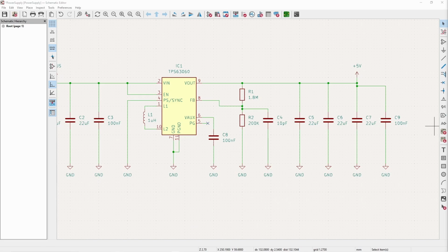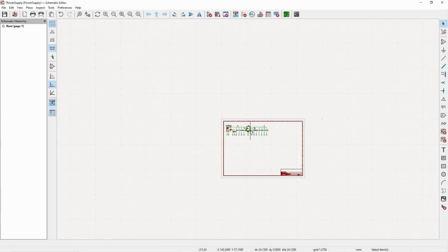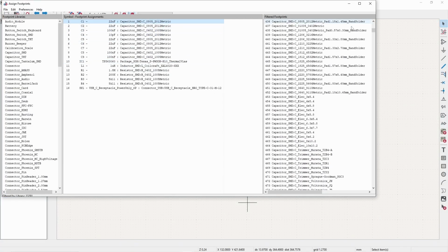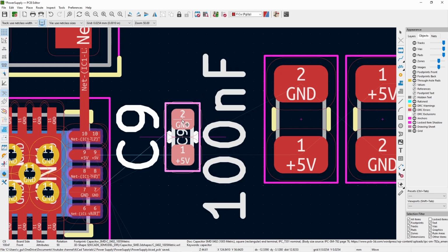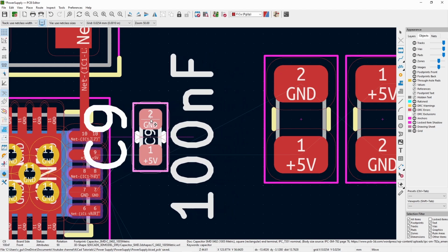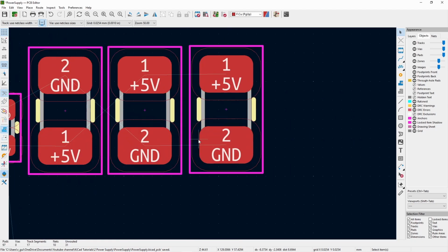I think I will add in a 3v3 LDO as well for low noise applications, just in case I decide to do audio for this channel in the future. And then finally, I want to include a TP4056 battery management circuit and a battery protection circuit as well. So hopefully you find this video useful.